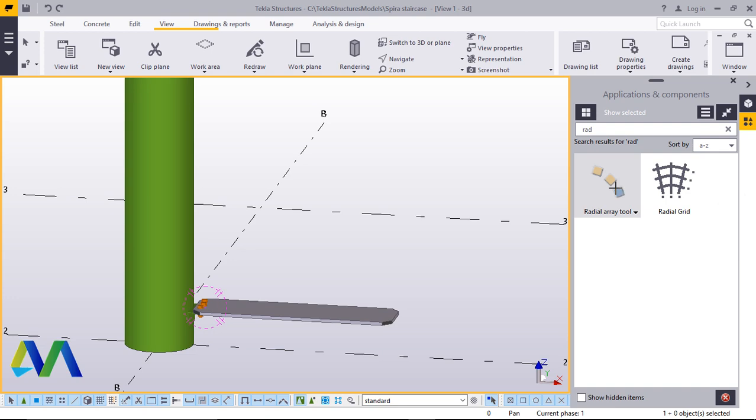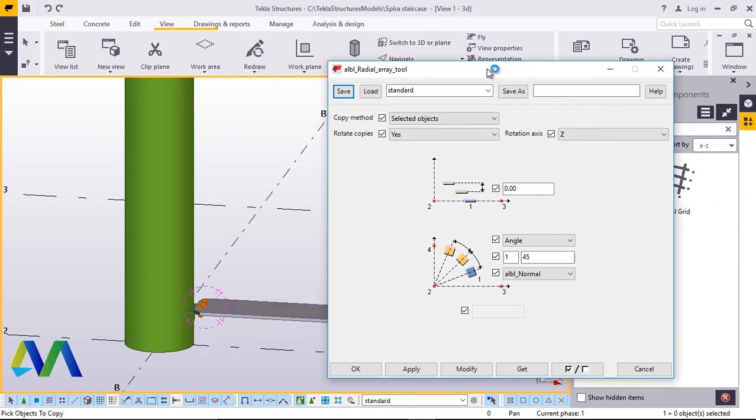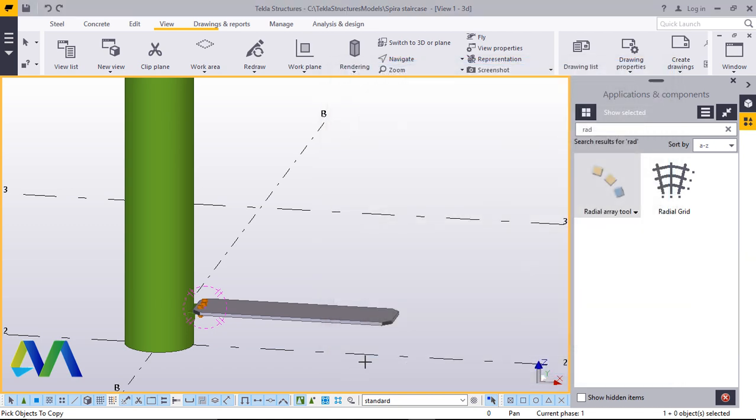Under rad I'll double click on that, bring this side, then change under radial array. We have a tool here. We have all this and the number of threads we need. Now from here we need a spacing, thread to thread 300, an angle of 20. We need 20 threads here, type there, and these will leave it at absolute normal. Then click modify, apply and accept.